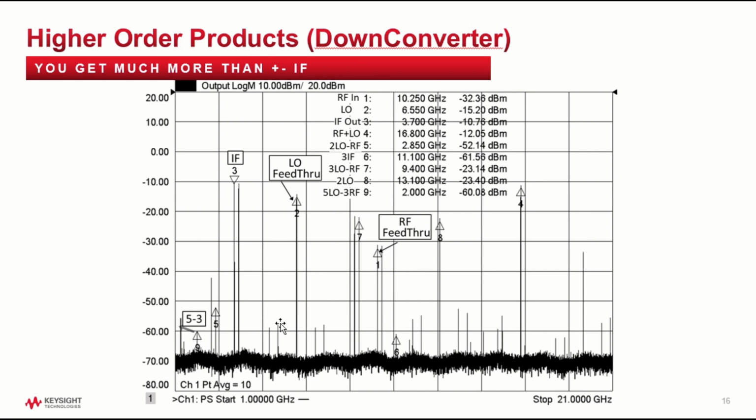Then what we're seeing down here is a bunch of higher order terms. I didn't identify all of them, but these are probably second order terms because they look like they shift 2 times for each signal. So we probably have a bunch of second order terms in there. And this just goes to show that when you make a mixer, you get lots and lots of things coming out of it, and you have to be really careful not to have those spurious signals, which are called mixer spurs, but I prefer to call them higher order mixing products, come out of your mixer.